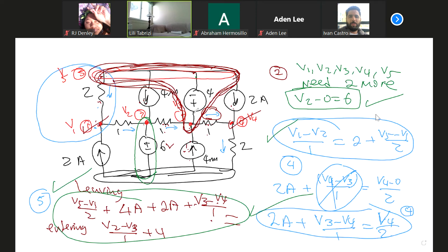I have a voltage source connecting node 3 and node 5, and the voltage is across, between. What is the voltage in between 2 terminals? It's a voltage between 2 terminals. Right? So, Leon, what is the voltage associated with 4 volts? It's V5 minus V3 equal 4. Exactly.